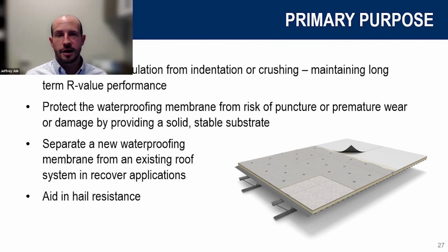Really, I would say there are three groups out there, similar to the insulation. We have high density polyiso insulation cover boards, gypsum cover boards, and then wood fiber is the other category, but that can be a lot of different things. It could be asphaltic boards, perlite, things like that, which fall into that high temp bituminous application for the most part. So for hot mop or heat welding, generally you're going to want to use an asphaltic board or perlite that are going to be very high heat resistance.